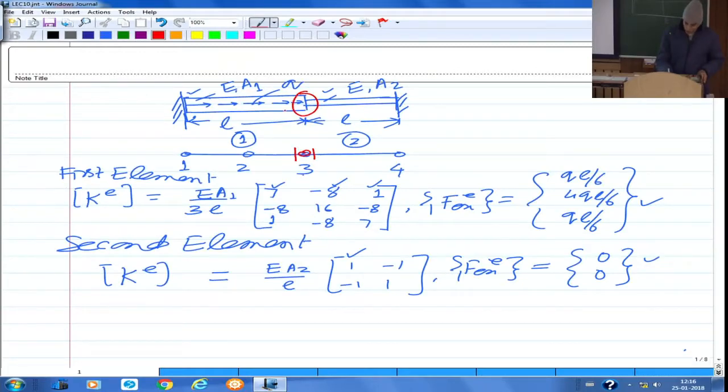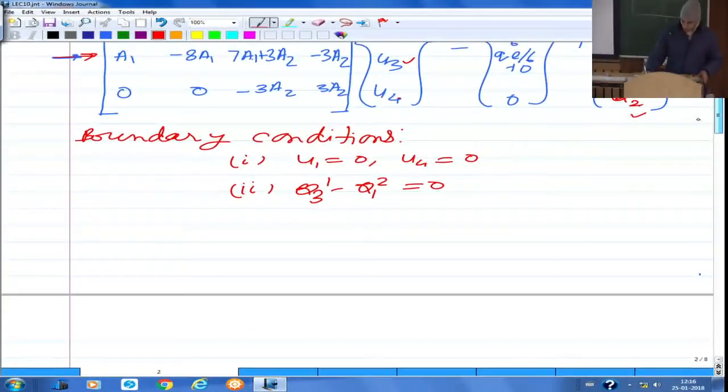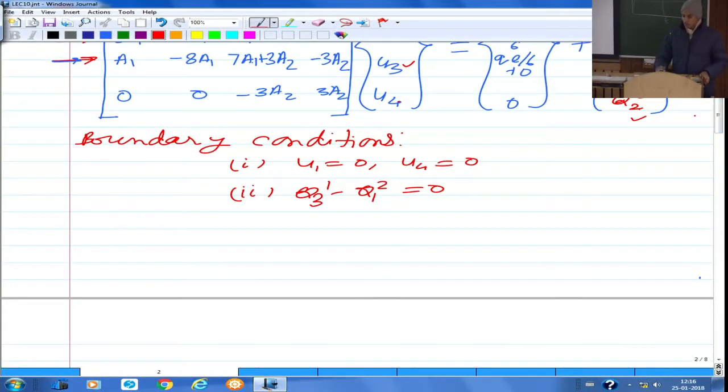So a little away from that, whatever we get would be close to reality, as long as the cross-sectional dimensions are much smaller compared to the lengths. But of course here we will have discontinuity because of that stress concentration, which we cannot get from this model, because we are idealizing the problem as a one-dimensional problem. So this is one question which was asked, a very good question to actually demonstrate this. So then, is there any other question in between?